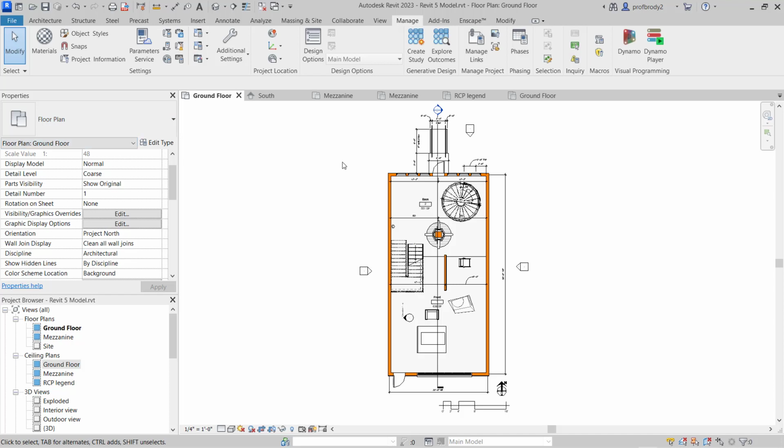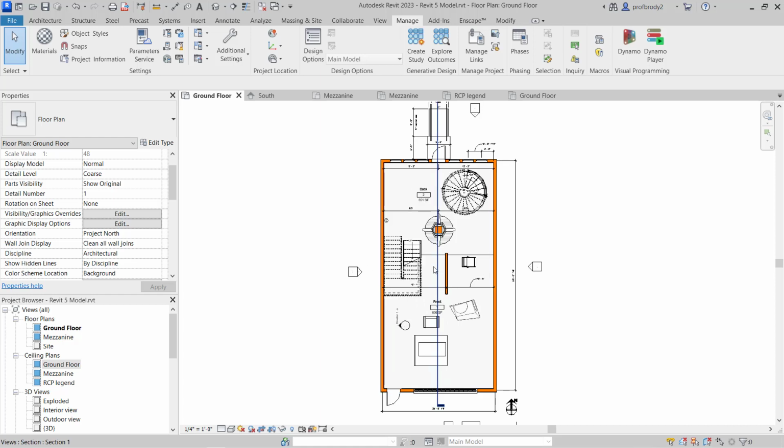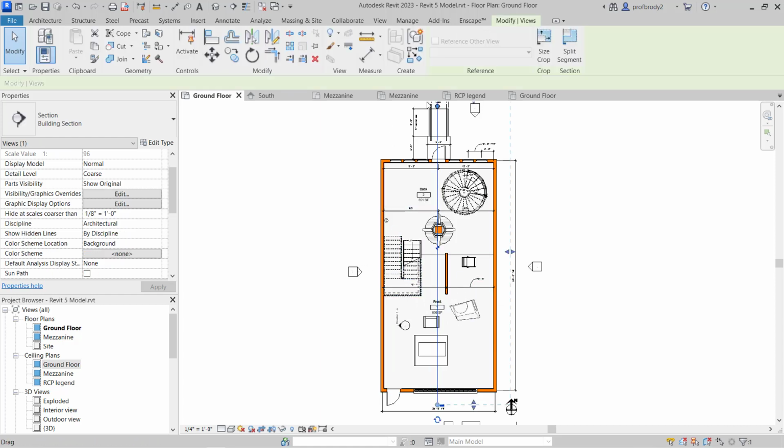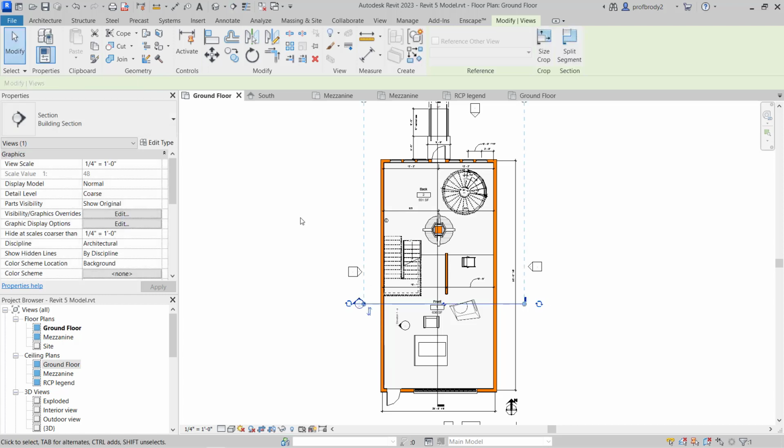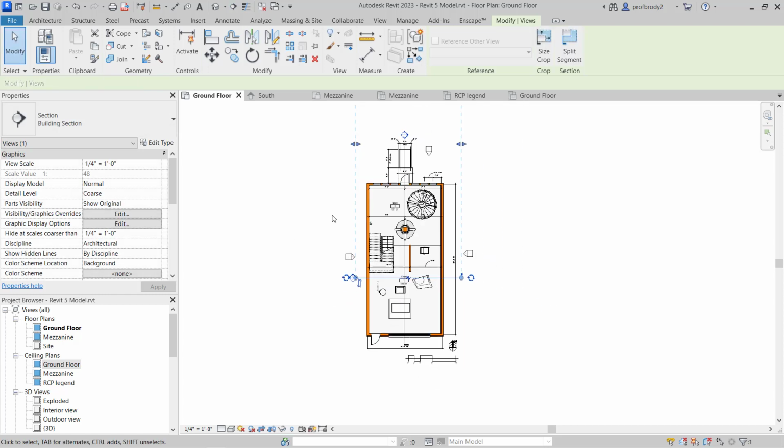You should also have both transverse and longitudinal sections in your project. Now, longitudinal usually goes the long way. That's the long part of longitudinal. We can select that section and choose Create Similar. We can also go to the View tab, and there's the Section tool. And you just click once to start and once to finish. Your section tool will create the drawing for you.